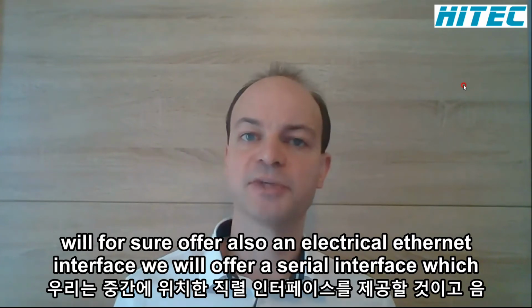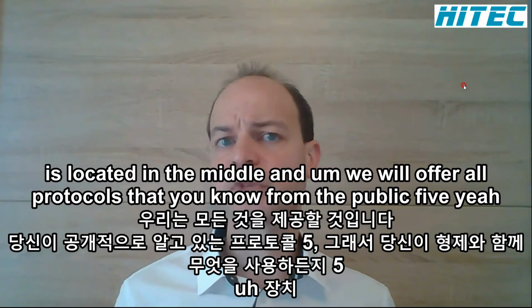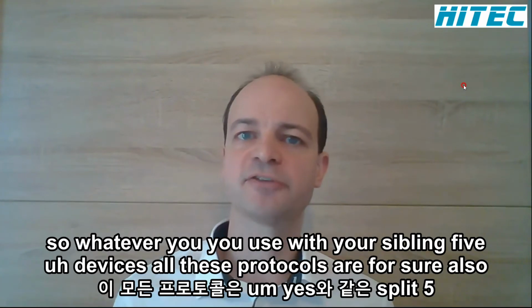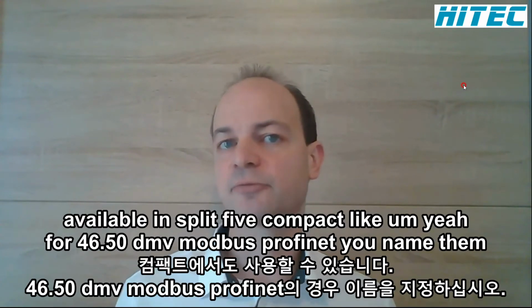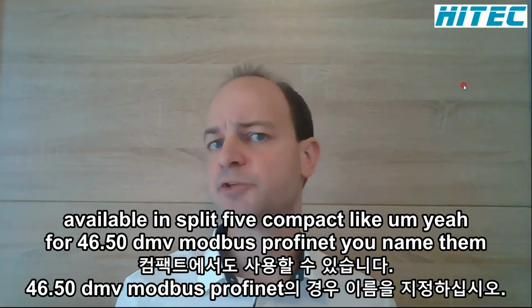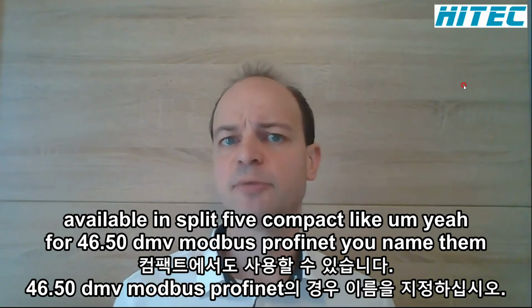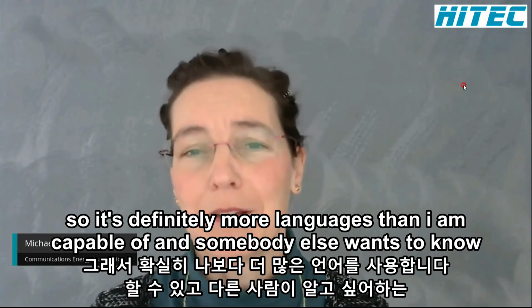And then in the next step, we will for sure offer also an electrical Ethernet interface. We will offer a serial interface, which is located in the middle. And we will offer all protocols that you know from SIPROTEC 5. So whatever you use with your SIPROTEC 5 devices, all these protocols are for sure also available in SIPROTEC 5 compact. Like, for sure, IEC 61850, DNP3, Modbus, Profinet, you name them. So it's definitely more languages than I am capable of.